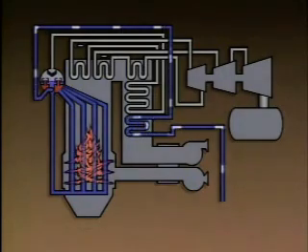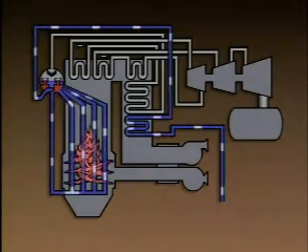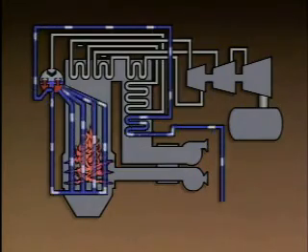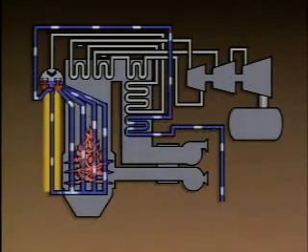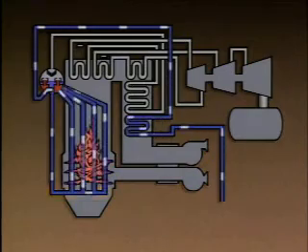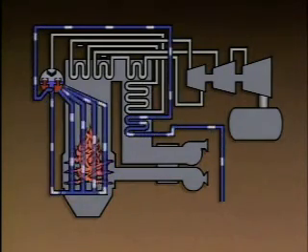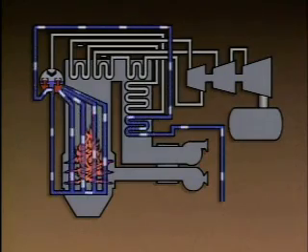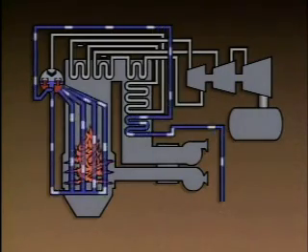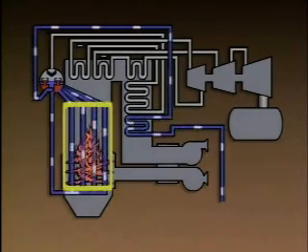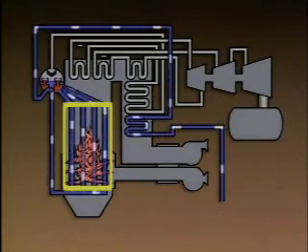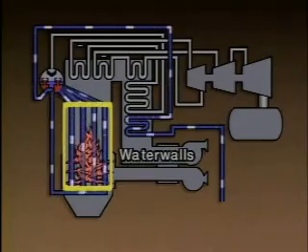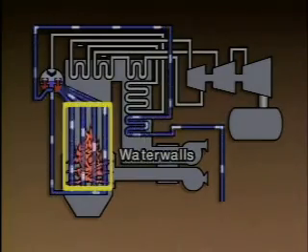The water continually circulates within the boiler through the downcomers, the lower headers, and the boiler tubes. A boiler typically has 2 or more downcomers and 2 or more headers. However, for clarity, this illustration shows only one of each. The lower headers supply water to the bottoms of the boiler tubes. The boiler tubes, which line the inside walls of the boiler furnace, are commonly called water walls. The water walls are exposed to the heat produced by burning fuel.